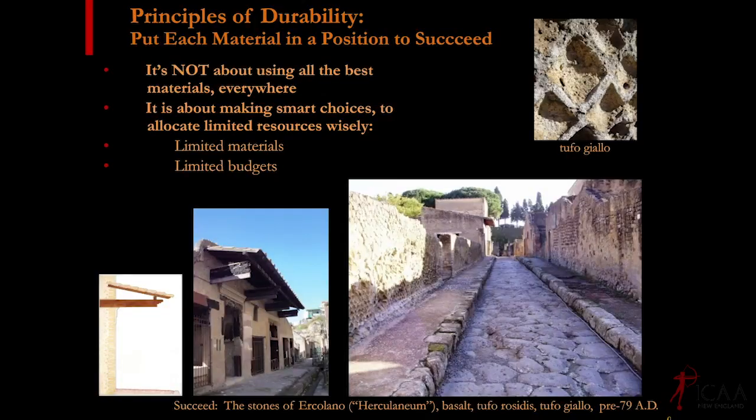So the way they made the stone more durable was big roof overhangs like you see here, and then a sacrificial coat of plaster on top of that. So keeping the water off it, and then if something's going to get wet and deteriorate, it's not your structural wall, it's just this sacrificial plaster parge coat.